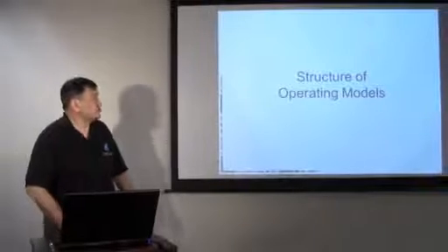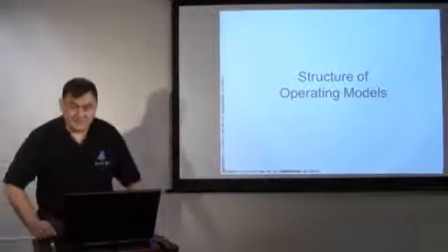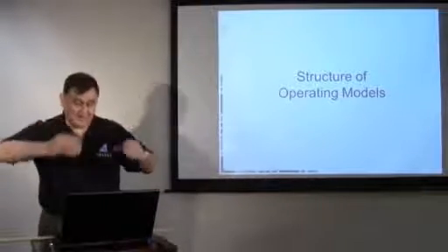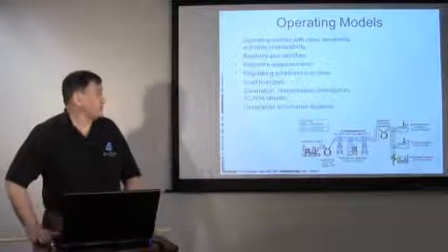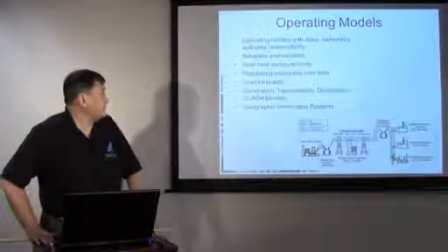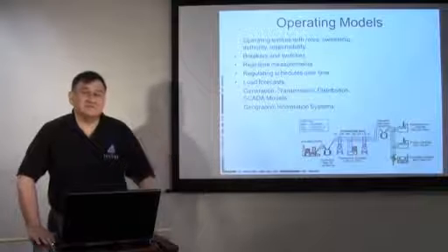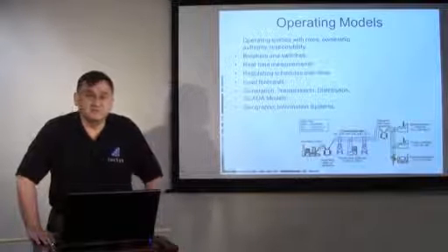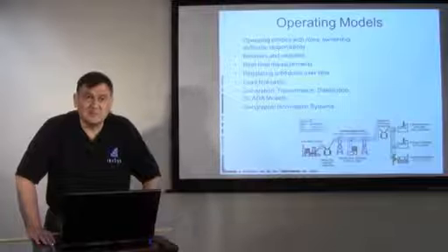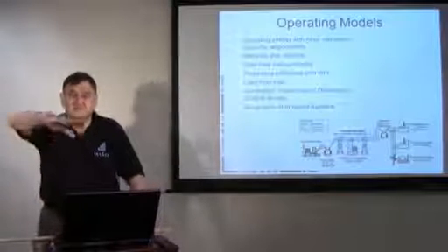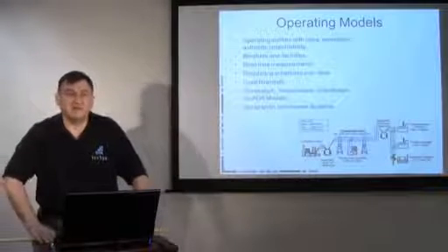So let's look at the structure of operating models. You remember we talked about how the electrical bus bar is really the key for planning models. But with operating models, things get a lot more complicated. We have different entities with roles and ownership and responsibility. We have to deal with the actual breakers and switches. We have real-time measurements. We have schedules for regulating values over time.